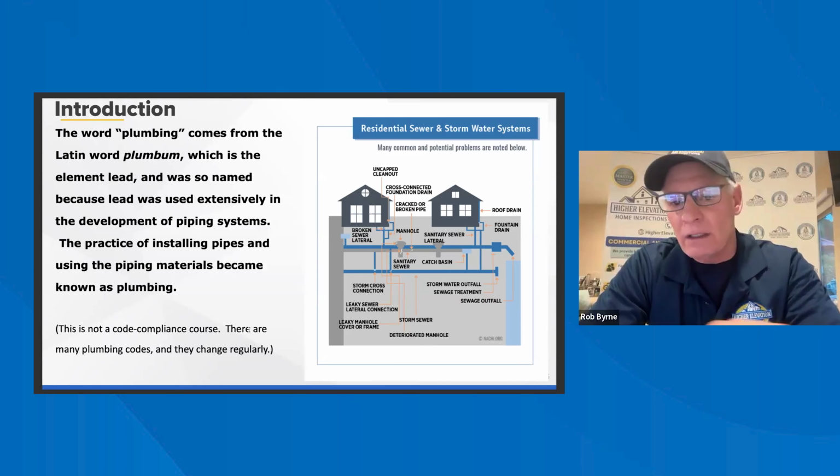Fuel shutoffs, all part of our inspections. Again, documented. We like to state it in our report, showing where the valves, the shutoffs are, and all of those kind of things. It's important. Again, we talked about earlier, a shutoff can be electric for the plumbing because it's a water heater. That would be the shutoff for the water heater for fuel source, because electricity is a fuel source. So you have the picture on the left is the shutoff valve for the gas. And then, of course, you have the temperature setting on the regulator on that section, which you can close off also.